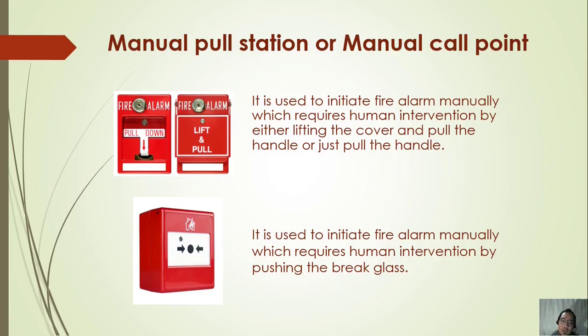Where we need to use single or double action, well, it depends, guys, on your application. Let's say your fire detection and alarm system is in a business occupancy, like offices. In offices, we're expecting that it's not open to the public, for people to just come inside the building, and it's not controllable. I mean, only employees will be there, most of the time within office hours. So in that particular occupancy, the best to use is single action.